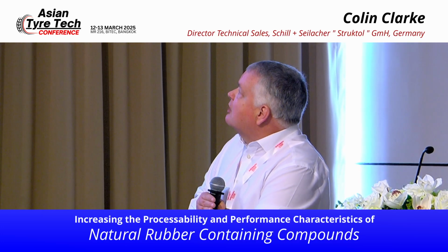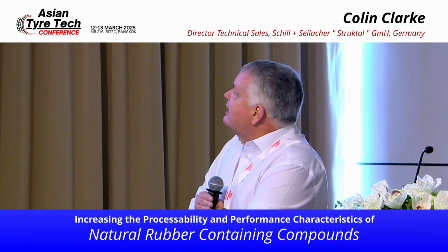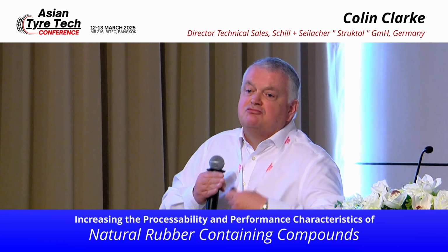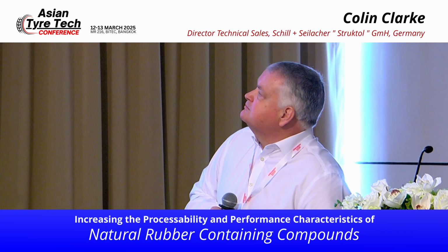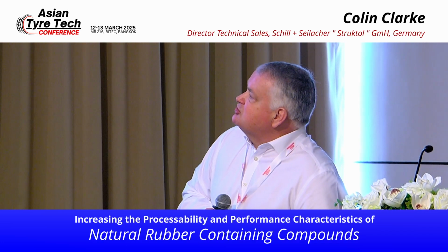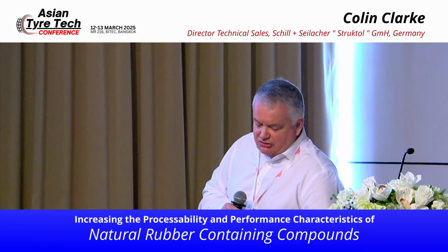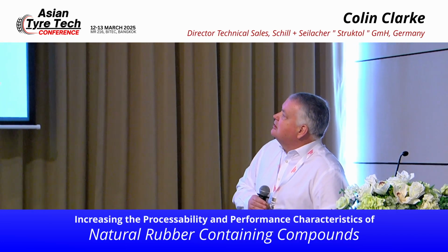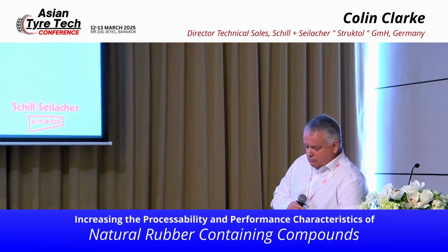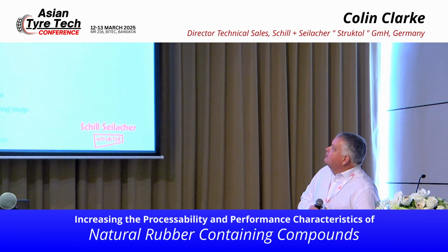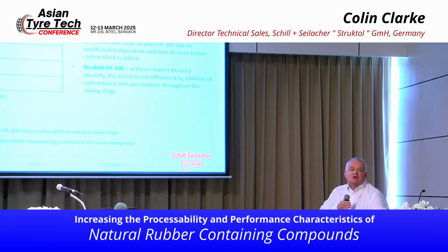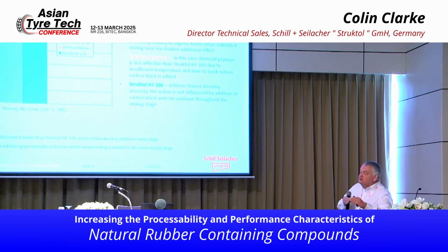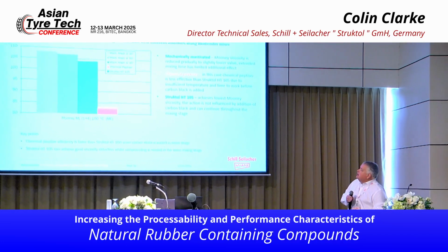But we add the two products right at the start, and then we add the carbon black in the same stage. So we're really shortening the process, we've eliminated the pre-mastication. Now let's look at the Mooney viscosity. So this is our mechanical mastication, 3.5 minutes, 4 minutes, 4.5. And of course, extending the mixing reduces the viscosity, but it's not that strong. It's just a little bit down.